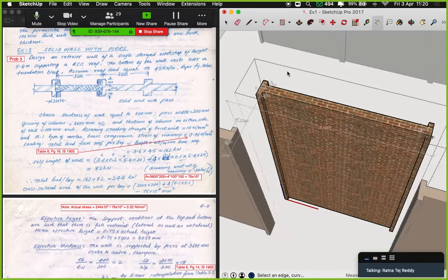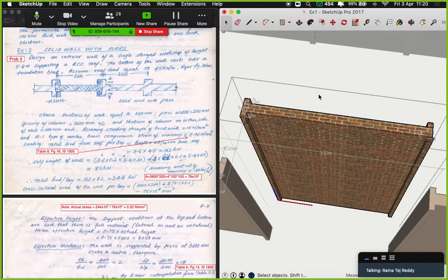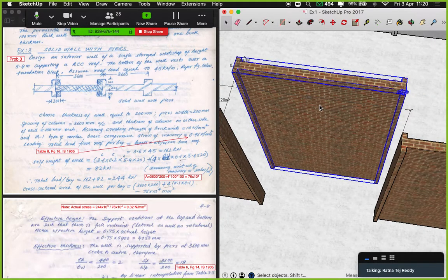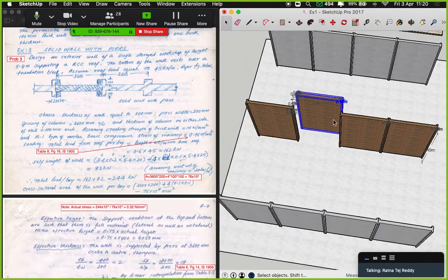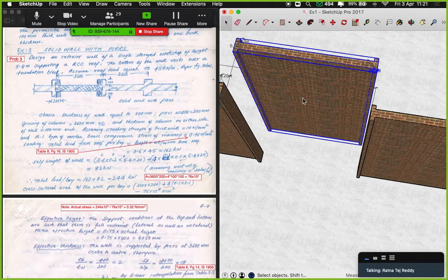So once we do all that, we get the total self weight of this unit, whichever you are seeing over here. Now similarly, it is applicable for all the bays out there. This is just for one unit over here. So the total load per bay is 162, which is nothing but the weight of the roof on a bay, plus the self weight, which is 82 kilonewtons. That is these two combined, both the projections and the wall. We get a total of 244 kilonewtons per bay. That is the total load happening per bay.